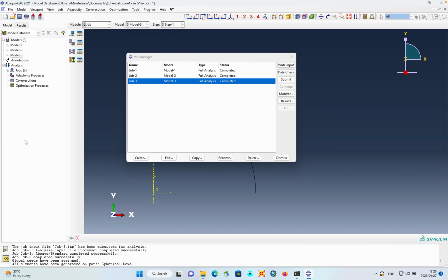So now this is mesh convergence. You see how much time I'm taking, and this is for a simple structure. Now imagine real world problems. If you do not optimize your computational time, you will never finish in time. Even in industry, sometimes you don't know if the solution you have is the right solution or not, hence why you always have to do mesh convergence to see if your solution is converging.